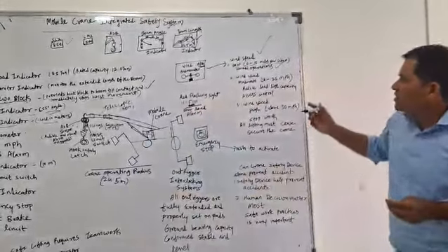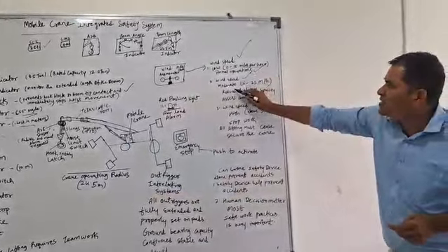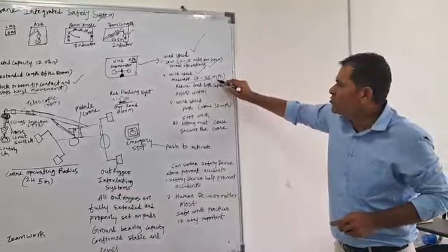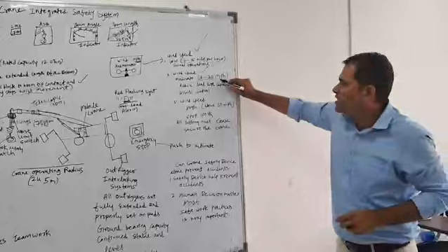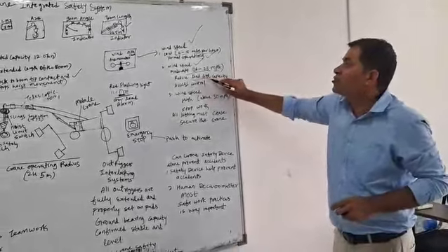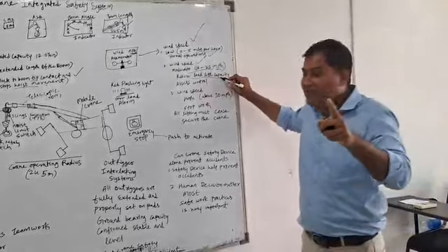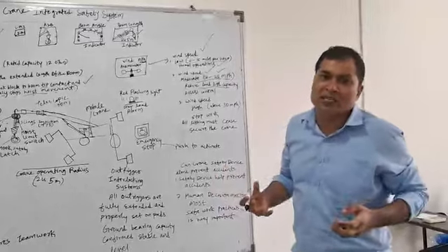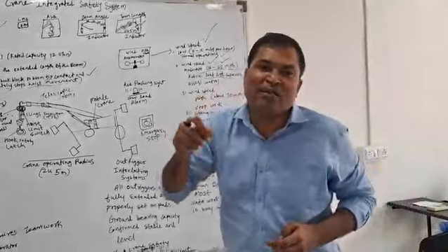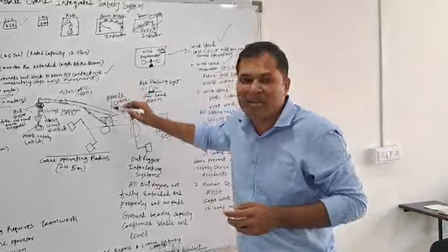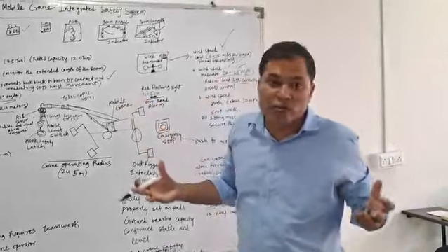Now the wind speed says 16 to 25 miles per hour. 16 to 25. The speed of wind is around 16 to 25 miles per hour. Then you have to reduce the load lift capacity. Now here it is very important. If the wind speed is too much, then you have to reduce the load capacity. It says the crane supports around 12 tons. So wind is too much